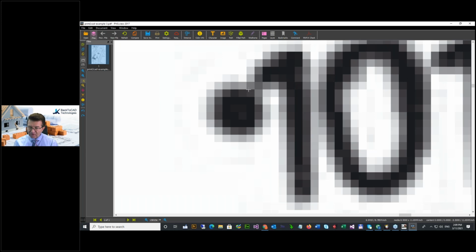Like this color will be our threshold. Go here on color info, click on it, and you see this is not a grayscale. This is RGB hexadecimal, but the value is about 40. Take every time the first number and remember it, 40.